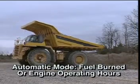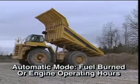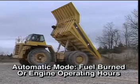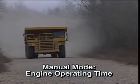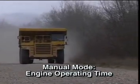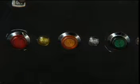With the automatic mode, the filter or oil change interval is determined by the maintenance interval value in fuel burned established by the calibration or by the number of hours of engine operation. With the manual mode, the maintenance interval is determined by tracking engine operating time. The maintenance monitor notifies the operator when the first of these factors reaches the predetermined level.